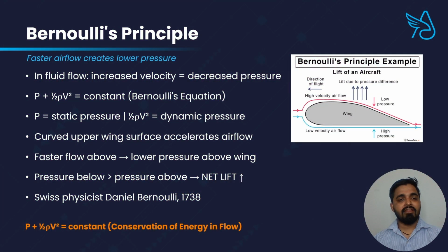You have probably heard the name Bernoulli, the Swiss physicist who gave the most important principle in flight. Bernoulli's principle states that in a flowing fluid, including air, when the speed increases, the pressure decreases. Let me make this very simple. Think of a river. Where the river is wide, the water flows slowly and calmly. But where the river becomes narrow between the rocks, the same water has to squeeze through a smaller space, so it flows faster. You can observe this at any river. Pinch the end of a hose and the water shoots out faster. Now apply this to a wing.